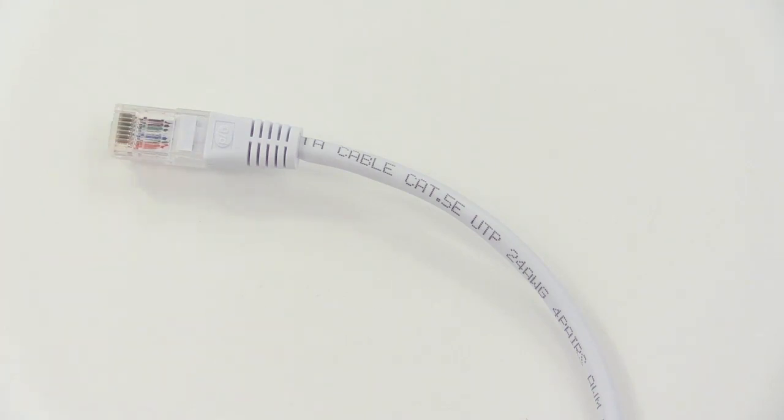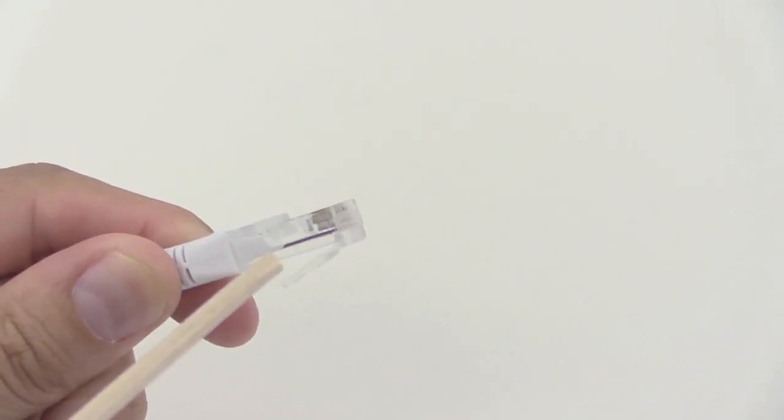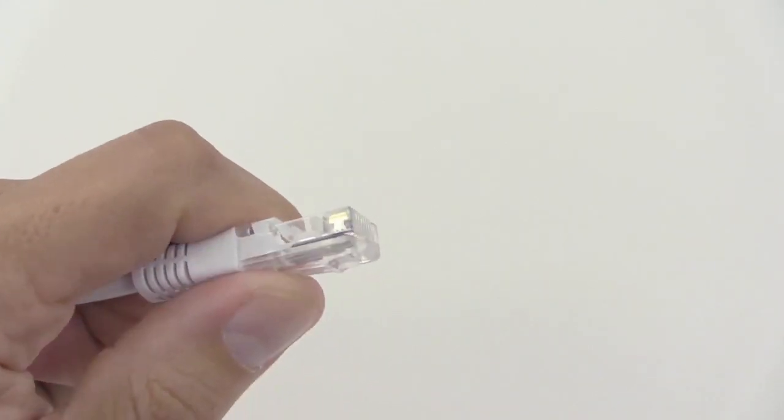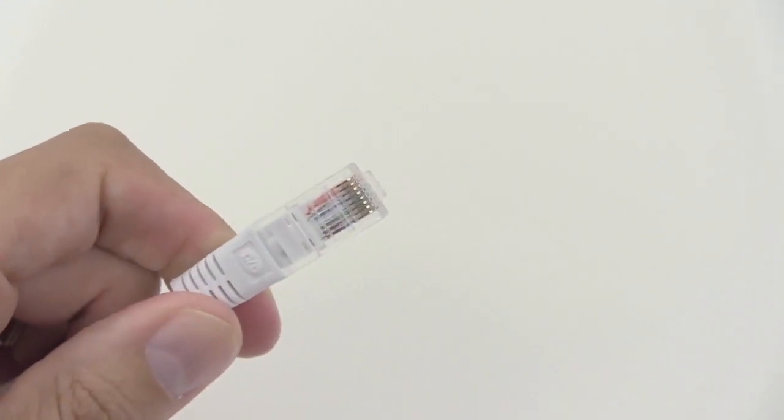And if we look at the plug a little bit more carefully here, you'll see that it's a modular plug and it has a tab, and that tab presses in and it allows you to lock the cable into place. And you can see the colored wires here. And these wires, you want them to be within these copper connectors. They need to be underneath those copper connectors in order to get good data connectivity. And you can see these wires go all the way to the edge here. If you look real carefully, you can see they go right to the edge of that RJ45 connector.